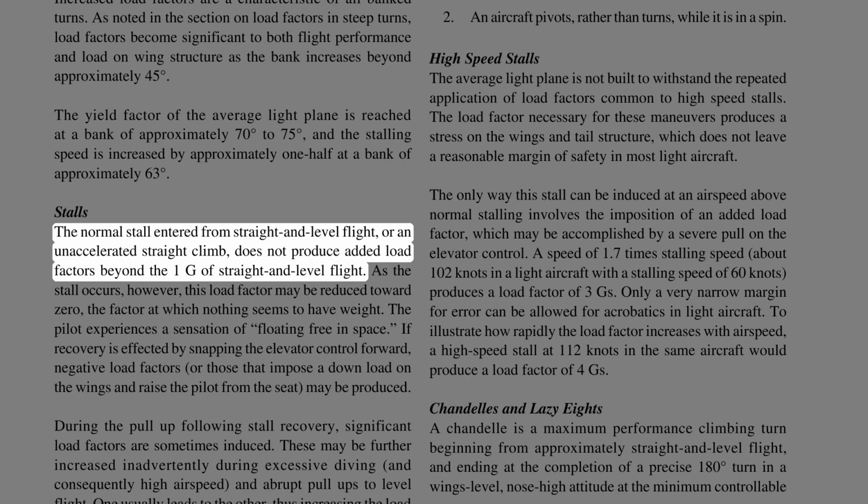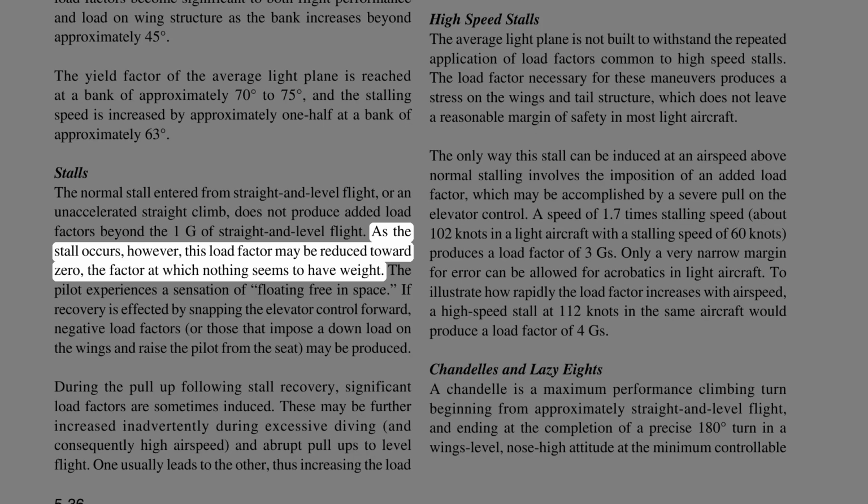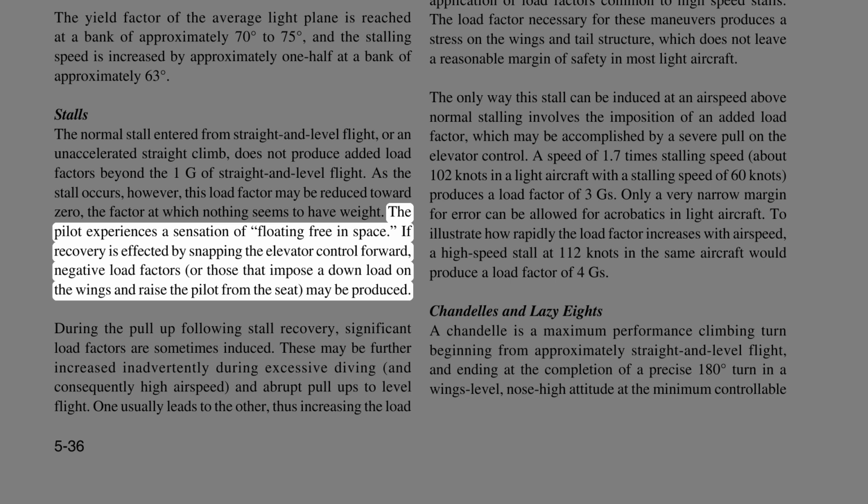Stalls. The normal stall entered from straight and level flight, or an unaccelerated straight climb, does not produce added load factors beyond the 1 g of straight and level flight. As the stall occurs, however, this load factor may be reduced toward zero, the factor at which nothing seems to have weight. The pilot experiences a sensation of floating free in space. If recovery is effected by snapping the elevator control forward, negative load factors, or those that impose a down load on the wings and raise the pilot from the seat, may be produced.